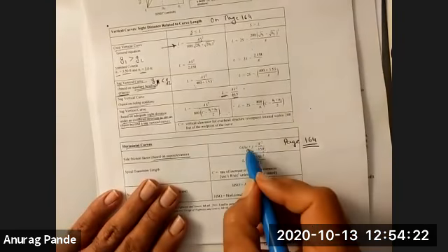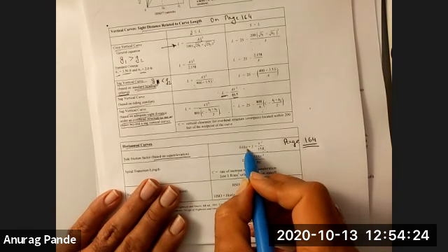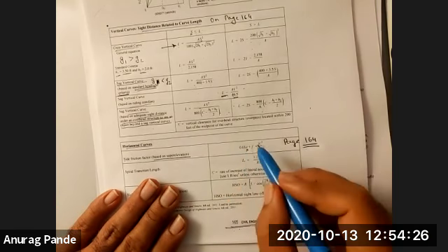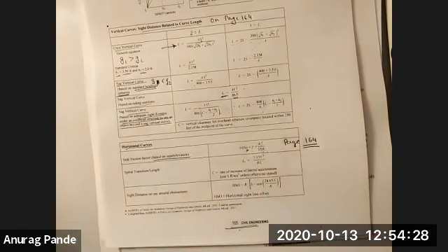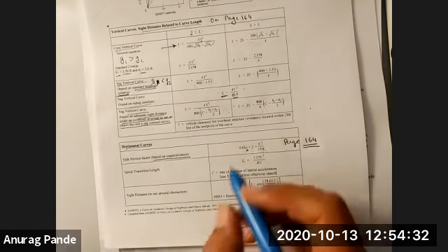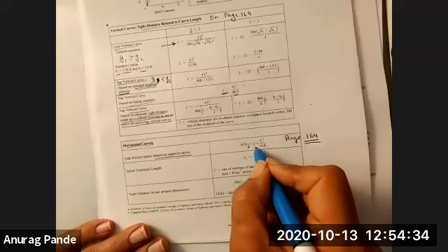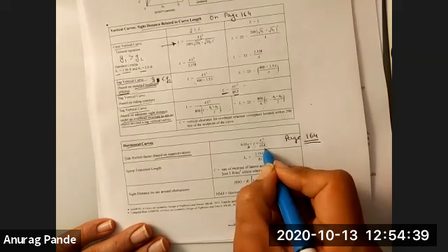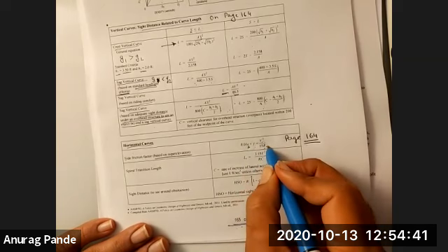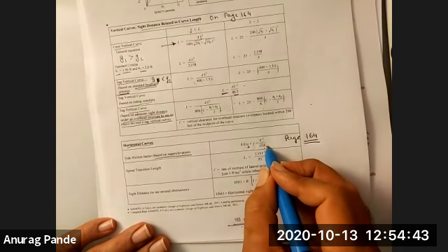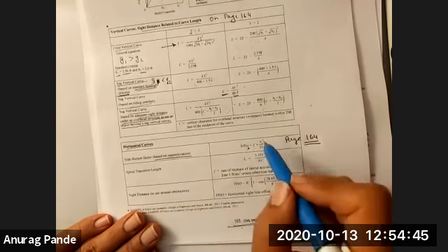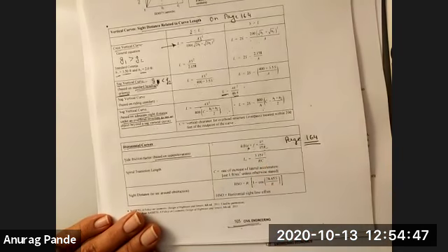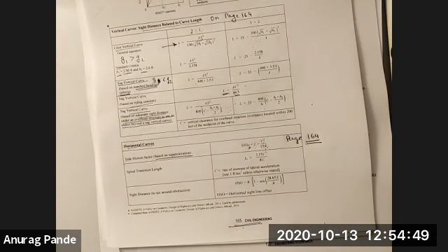So go back to page 164. You can solve for any value here, either for e, small f, capital V or capital R. Any of these could be worked out in the form of a problem. You could figure out what the side friction factor has to be if you're providing a certain super elevation and you know the design speed and radius, or you might be asked to figure out the minimum radius that you need to provide, or the maximum design speed that you could provide on a certain road given certain values. Okay.